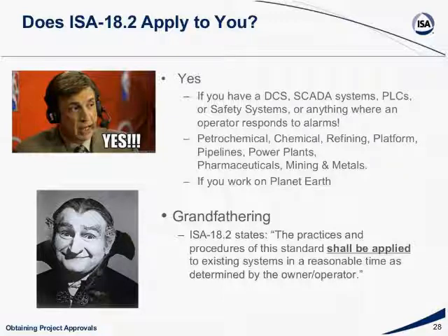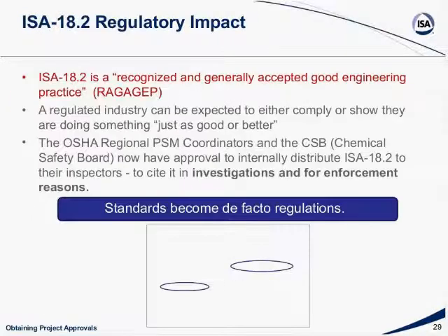Because if something happens and OSHA comes in, the definition of reasonable time will not be left to the owner-operator. It's really going to be what OSHA says it is. And so really the sooner the better. Yeah, you are grandfathered in, but you're only grandfathered in until something happens. If something bad happens, you're kind of not grandfathered in anymore. So there's a sense of urgency to get with the program and have a good alarm management program at your facility.